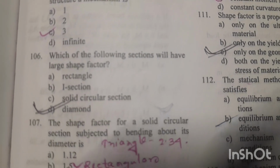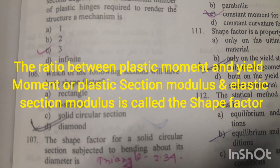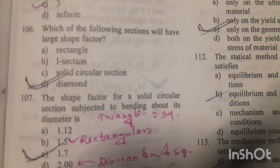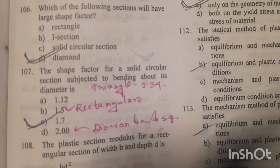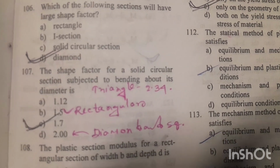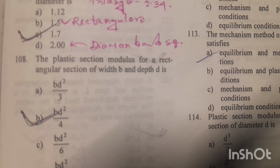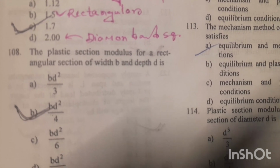Question number 106. Which of the following section will have large shape factor? Diamond section will have large shape factor. Option D is right answer. Question number 107. The shape factor for the solid circular section subjected to bending about its diameter is 1.7. Option C is right answer. Question number 108. The plastic section modulus for a rectangular section of width B and depth D is.